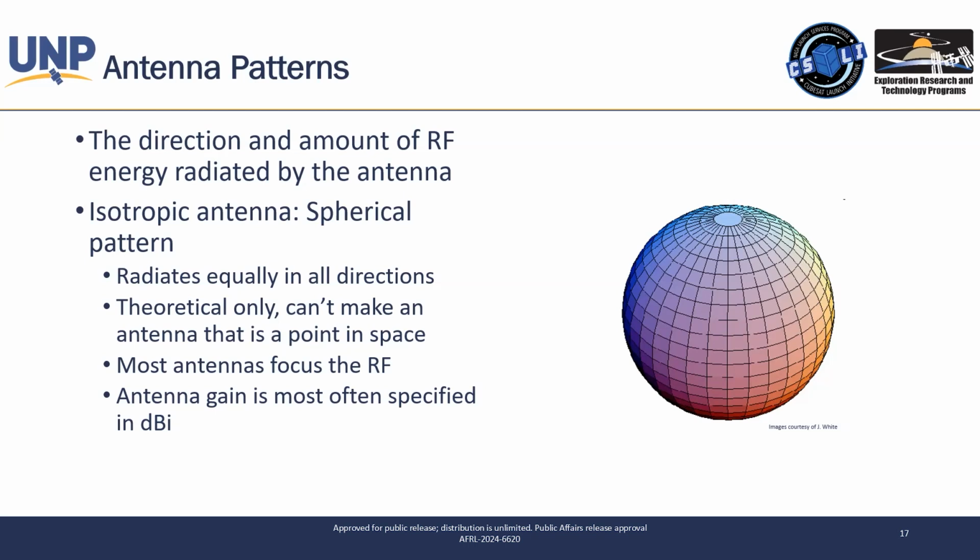So when you radiate from an antenna, if it's radiating in all directions, then your ability to receive comes down a lot, right? Because most of the power density that you transmitted goes out in directions you don't care about, or you don't have antennas, right? It's like you only have one antenna somewhere. And so it's going to be a design decision where you're going to want to close link with your satellite at any direction. Keep in mind that having all those directions means you're going to have a much weaker signal, which means a lower signal to noise ratio, which means lower capacity for the channel.